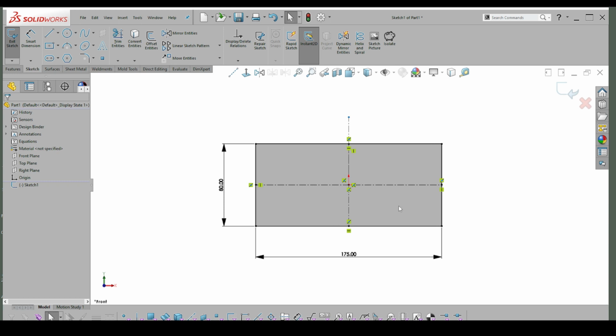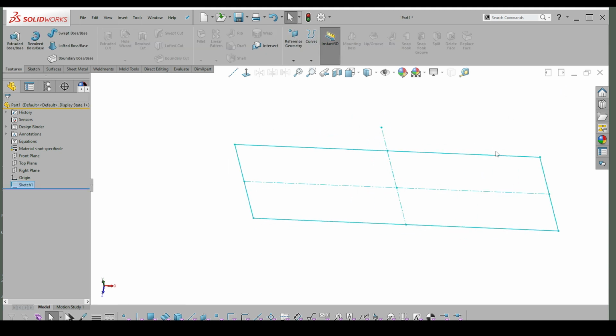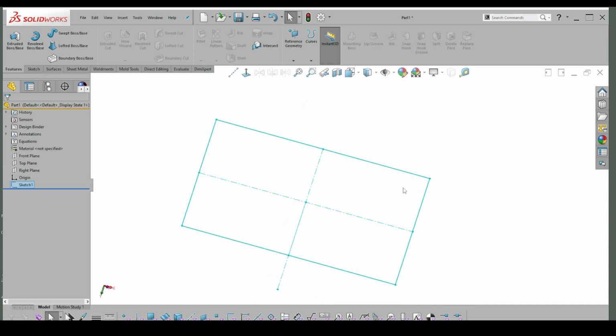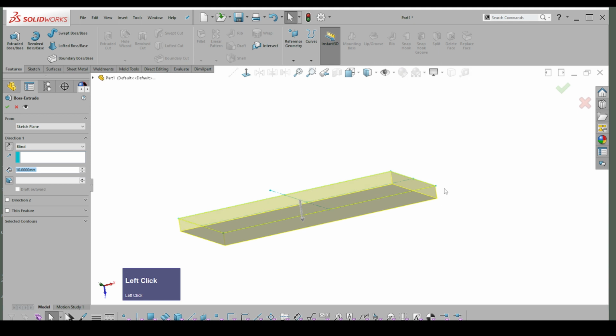So the basic principle to follow for best practice in modeling anywhere is one sketch per item. Now on Thursday I had suggested, or I had done this sort of single block and then had exited that and then used that to extrude a boss, right? And I think I made this 20, something like that.